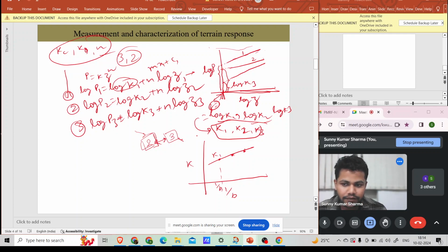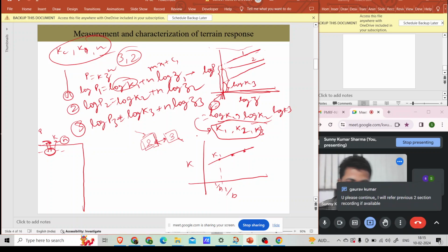But I'll give a brief of what this pressure-sinkage relationship is. We have some plates from the Bevameter. We place this plate on the soil, and our aim is to find the modulus of sinkage k and the exponent of sinkage n. And the relationship for this is pressure, which we are applying, which we obtain from some sensor, that is, what pressure we are applying.